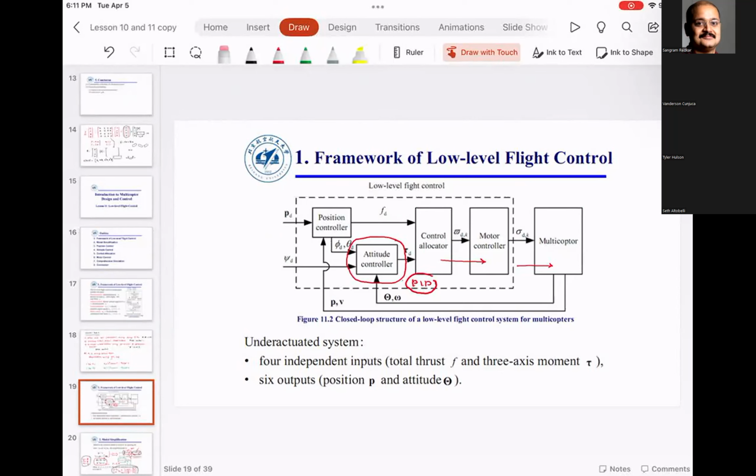What would that moving average do? That moving average would actually do a low pass filtering on your output and give you signals that are sort of constant. So that actually would make your life a little bit easy.